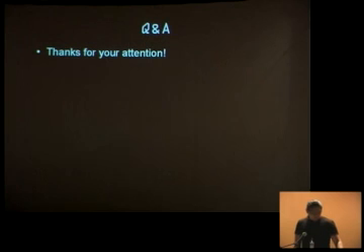Typically what these things do is they give you a number on the screen that tells you how good a connection it is, right? So sometimes it'll beep, and you read it, and it says 20 ohms, because its threshold is like, say, 100 ohms. You say, well, that's probably a resistor. You're looking for 0 ohms, and you just keep on beeping around until you see the 0 on the screen, or 0.1, whatever it is. So yeah, it's a good question, and sometimes you do find false positives.